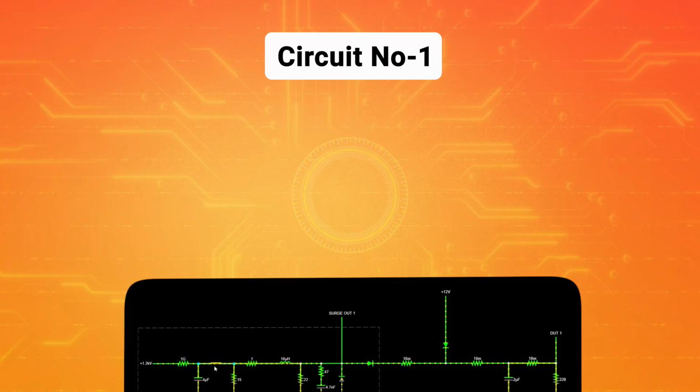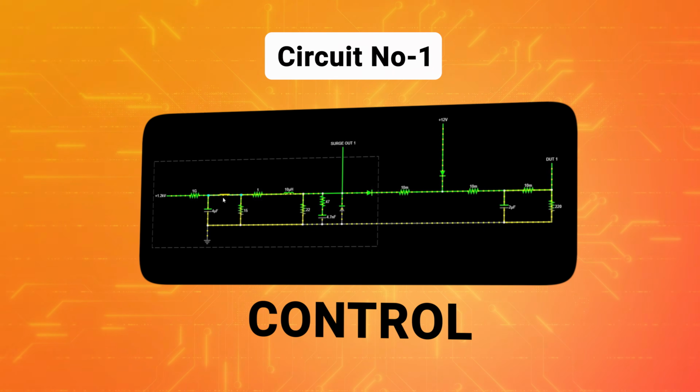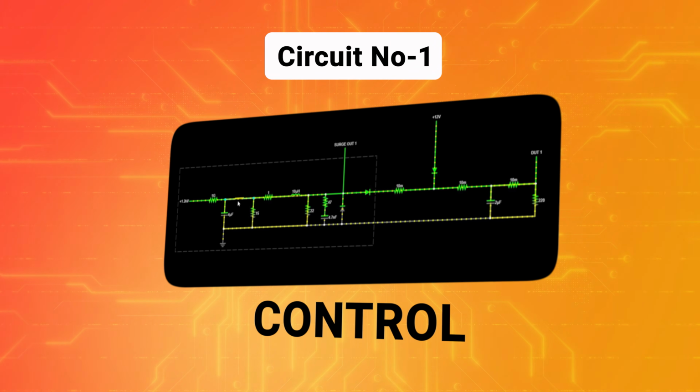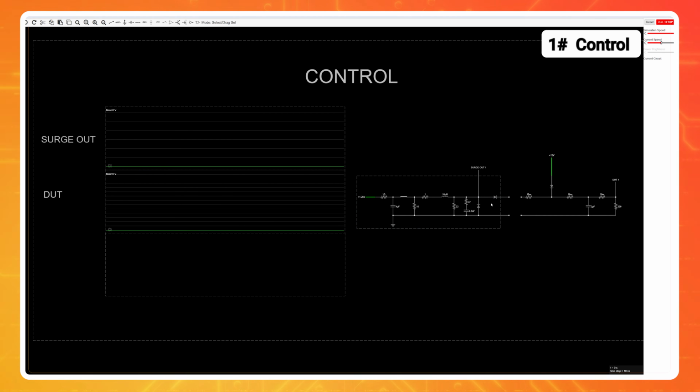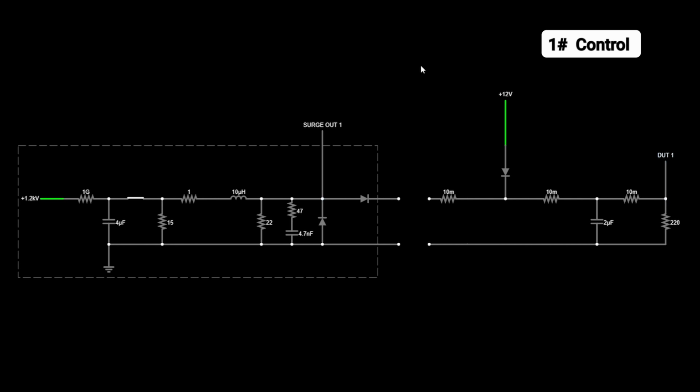So the circuit for the surge generator is super similar to what is in the IEC standard. I added a couple blocking diodes just to prevent any ringing and to prevent any backflow into the generator. And for the device under test, or DUT, this is simulating the input and then the general circuit and component load of a circuit board.